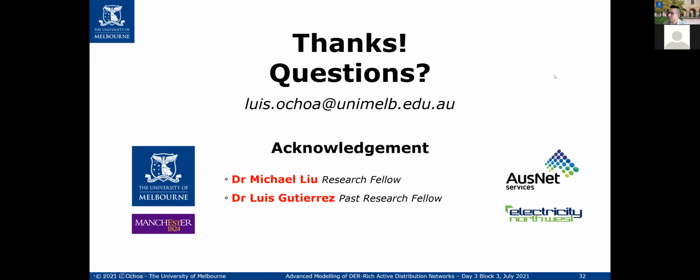Okay, now there's a question related to OPF, and I want to answer that live. So here's one: OPF here is a one-time snapshot optimization. Correct. The inputs of OPF are current time t, warm start, and it sends set points to the real system at t. Yes, but the optimization is under calculation, and the system could change load. Yeah, that's true. Which means the set points are sent later, not automatically. Right, that's absolutely correct.